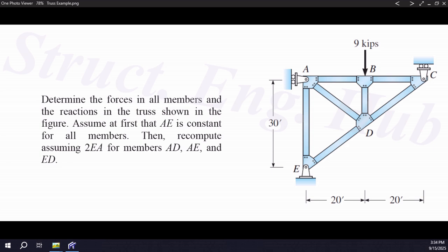Internally indeterminate trusses have additional web truss members, usually forming crosses, which is not the case here. The hand solution of such a truss involves choosing a support reaction as a redundant, drawing a primary and a secondary structure, then calculating all truss member forces on these structures in order to apply the virtual work formula to calculate the required deflections. These deflections are then used to write the consistent deformation method compatibility equation, which is then solved for the redundant. I will now demonstrate the solution procedure using the computer program.